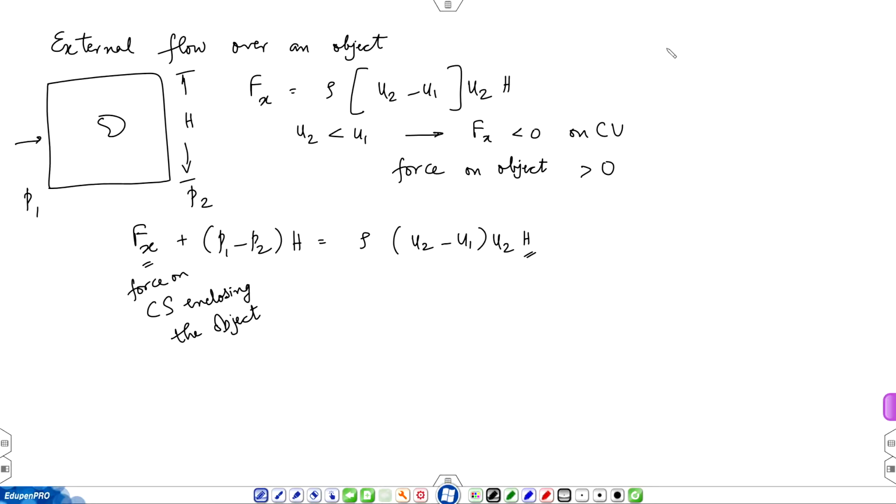Now, let us note this approach is often used in measurements to estimate the force. So, if you think of force measurement in solids, let us say a spring, you apply force and you want to measure force, what do you do? You apply it on the spring and measure the displacement, which times some property of the material gives you the external force. So, force is often measured through its response from a standard material. So, spring is like a standard material with a known stiffness.